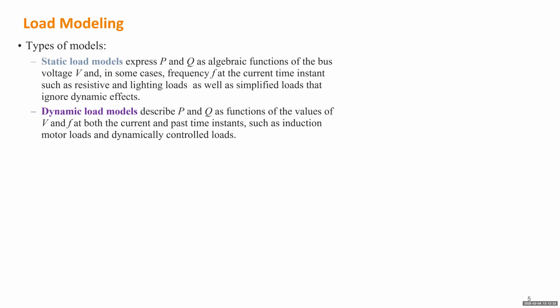Okay, so it may integrate some differential equation. By solving the differential equation, you can have the trajectory of the load, and then you'll find the current time instant that will tell you more accurate information. So in such a case, such a dynamic load model can be similar to generators. Like a generator is not a static device, it is a dynamic device.